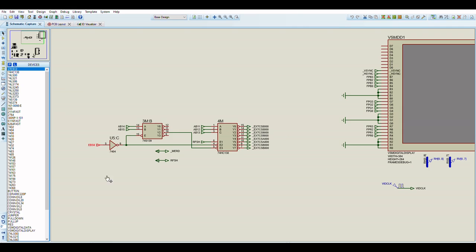This basically asserts that if the first or 0th bit of the extended memory bus is high, then it will allow me to start addressing the RAM, which was the original RAM on the Bomb Jack board, but also some of the extra RAMs that I've been memory mapping into this space here.